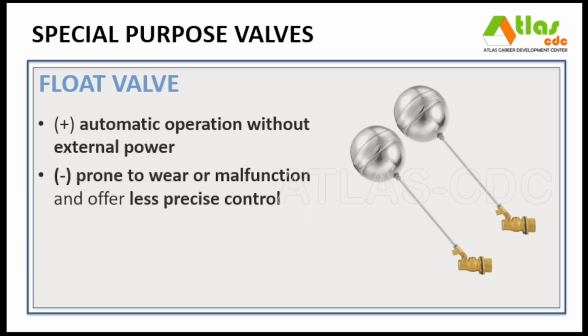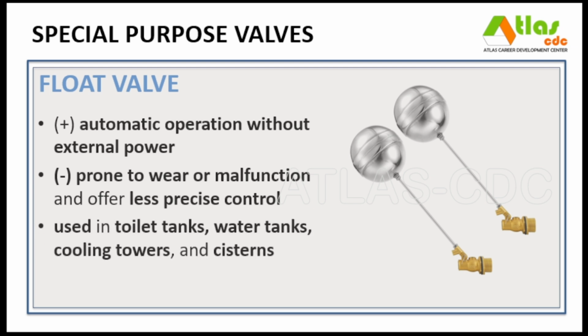However, it can be prone to wear or malfunction in dirty or high-pressure conditions, and may offer less precise control compared to electronically actuated valves. It is typically used in toilet tanks, water tanks, cooling towers, and cisterns, differing from other valves by its passive, level-dependent mechanism.